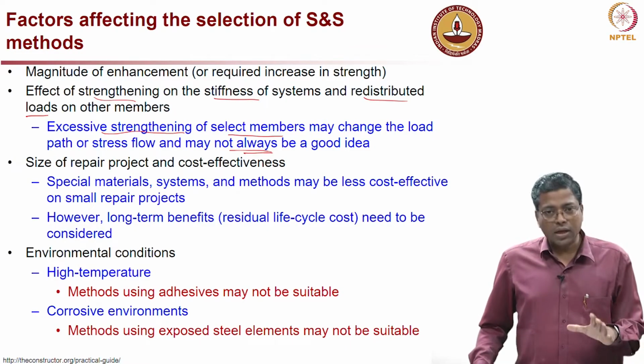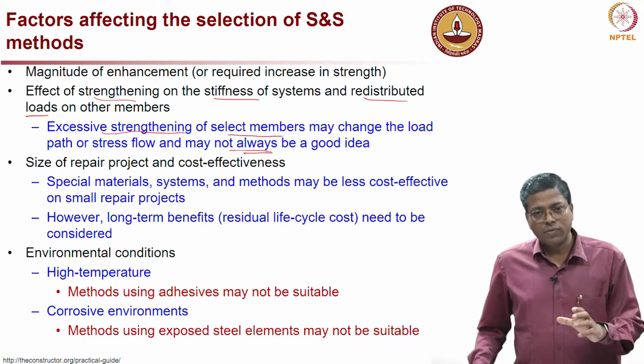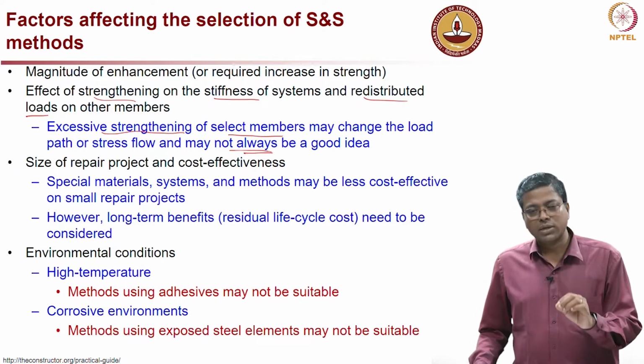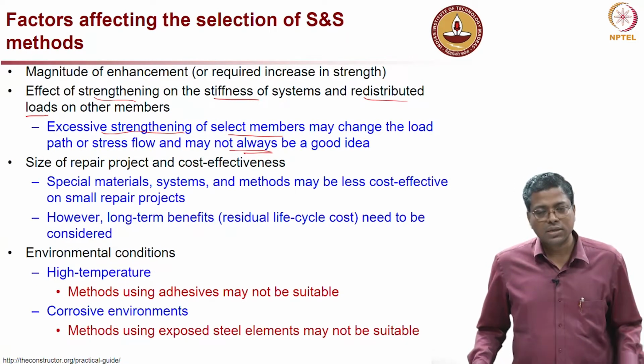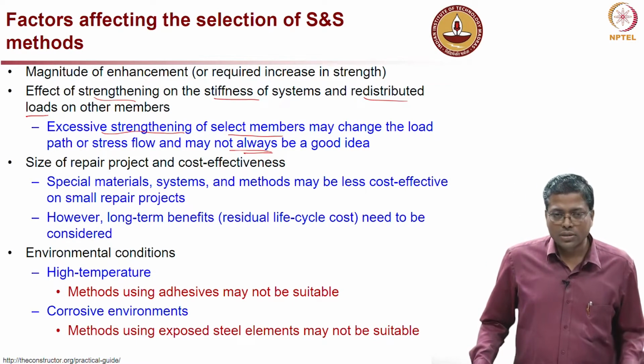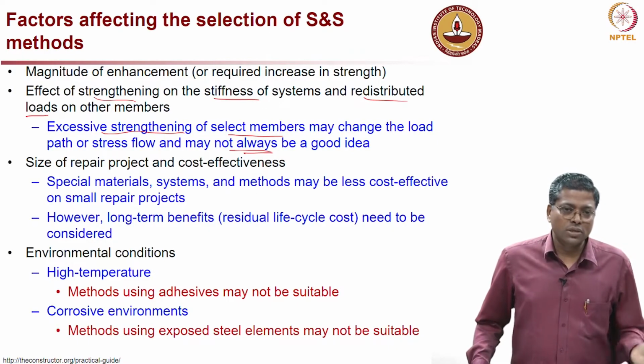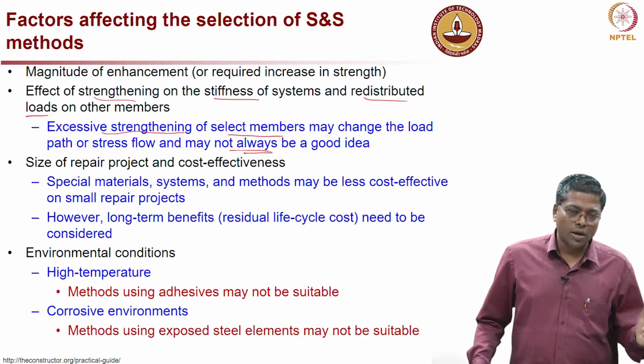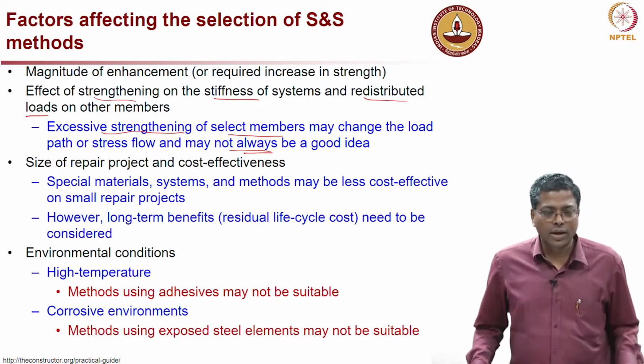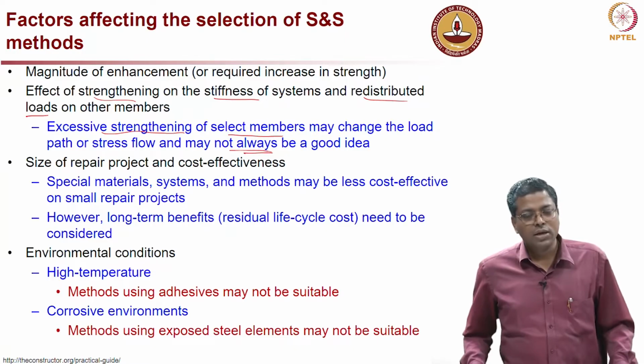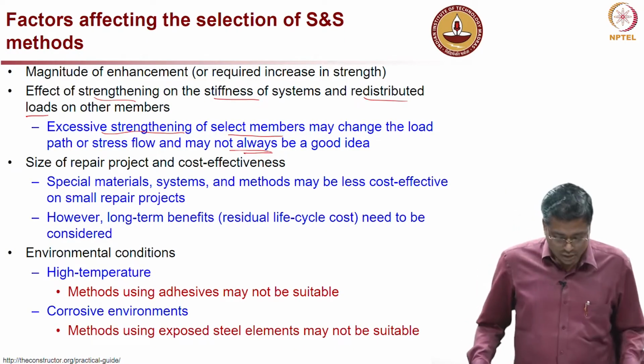The point I was mentioning is that sometimes there is a tendency for on-site personnel to just change the type of reinforcement from a lower grade to a higher grade based on availability, without really consulting the structural engineers.